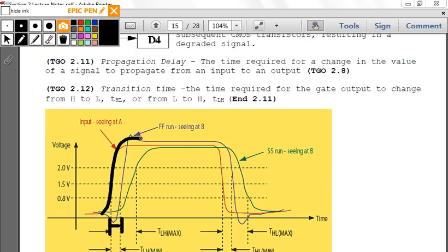So let's say you're doing the same thing where you have 1 and 1, and if you haven't properly coded it in, it could possibly change. Remember we were talking about that delay, we showed it in VHDL, we have this slight blip in time. So if we're running at a high frequency, I think this is what you were talking about a couple of classes ago, we can have an instance where if we don't properly ensure against a race condition, it'll go down a little bit, but then now it has the right value, so it'll come back up. And that's when we start getting the correct calculation. So that's an example of how the transition time affects the synthesis of a digital circuit.